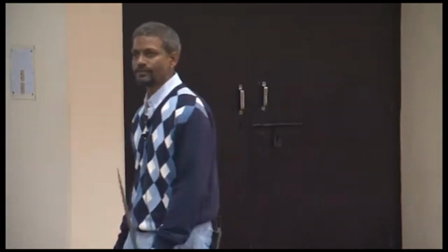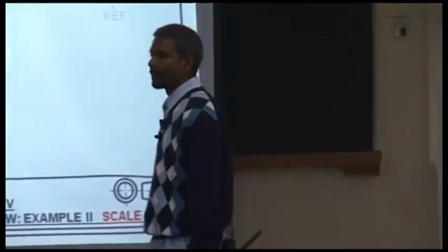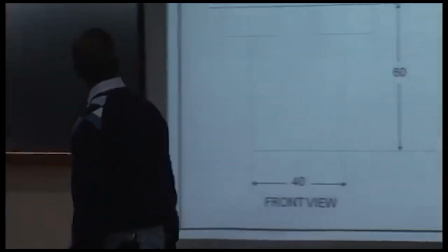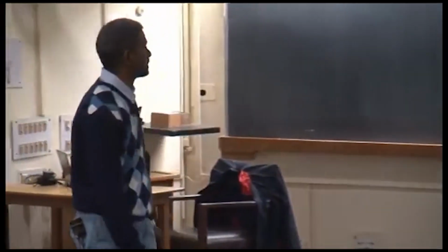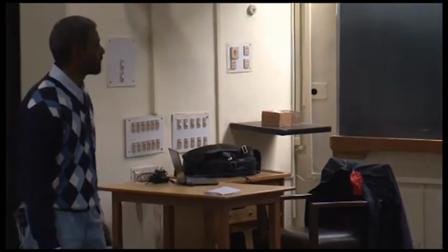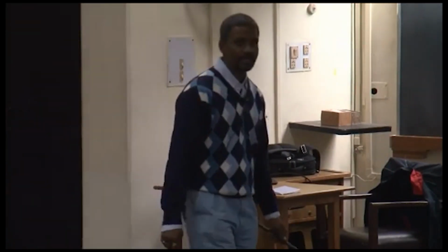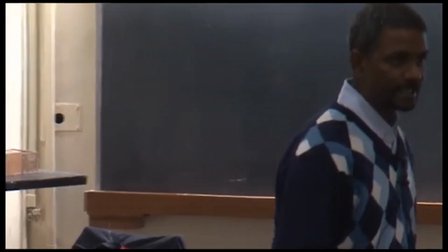And then start relating the top view to the side view using projections. 45-degree line. Okay, go down. Relate the side view to the front view as well. That's your reference plane in the side view. What would this projection correspond to?